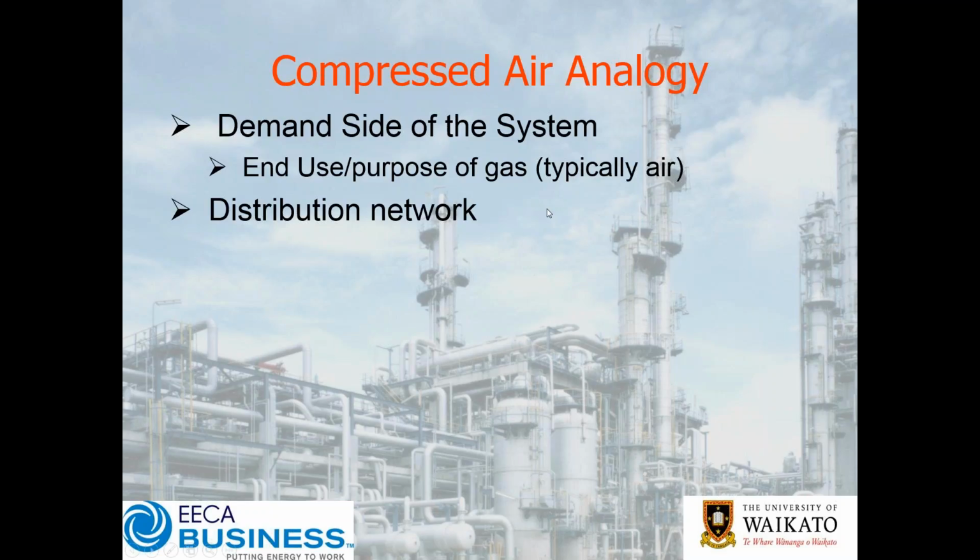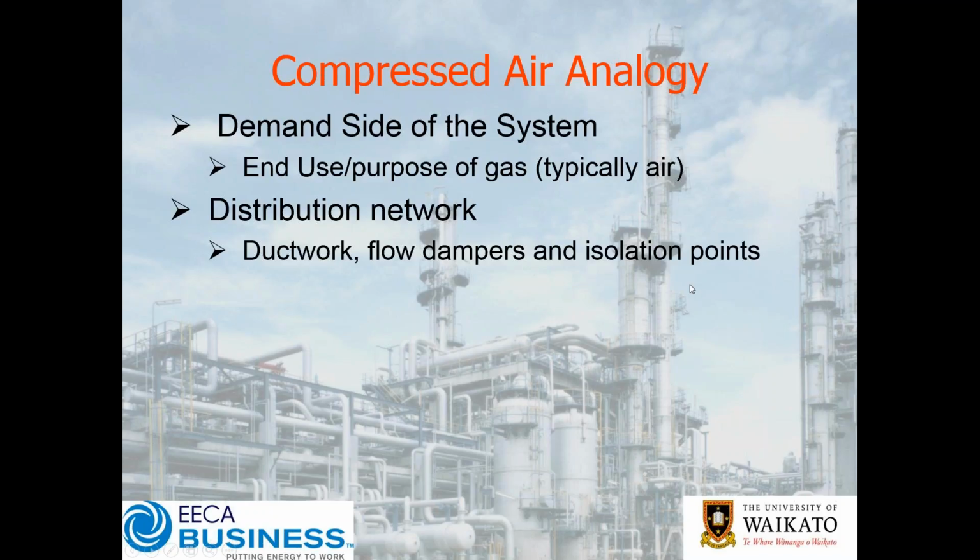We've then got a distribution network that we need to consider in terms of, well, where does the air and particulates, if they're picking up particulates, or the heat get conveyed? Can it be recovered? There's a whole network here in terms of ductwork. There'll be flow control dampers in some situations. Sometimes it's very important to also consider isolation points. There's plenty of applications out there where the airstream, as you pick up particulates or waste, can then pose a fire risk, and so you need to give consideration to isolation points for safety or for cleaning.